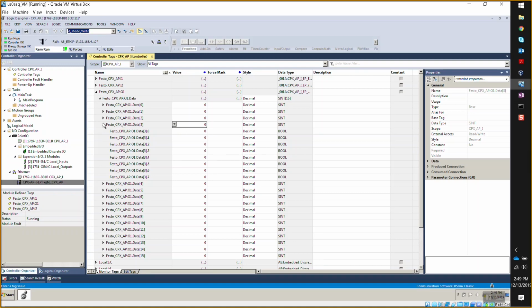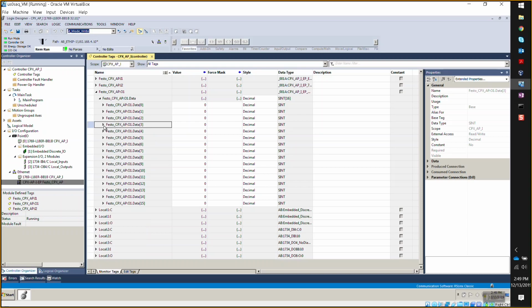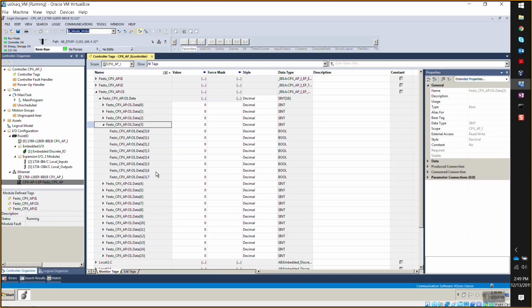It's just a matter of picking the right assembly instance. Got it. This is pretty cool, because that way I can set the data in case I need to expand I/O on my machine. I can do that later, and the data is already there. Right. So from a practical standpoint, that's good, because then all of my I/O is not shifted whenever I add an additional module.